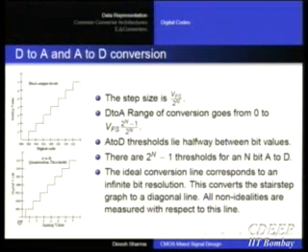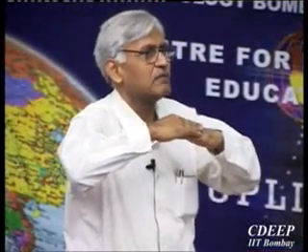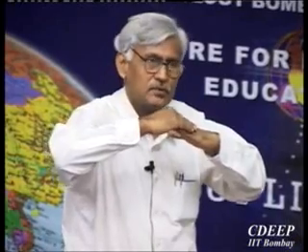Okay, this is the shift because the whole digital word spans an entire range. Okay, so this part is important. Sometimes when you have feedback, this could be even significant. Now, if I had a very large number of bits, then what will happen? This step size will become smaller and smaller. In the limiting case, if I had infinite bits, this would become just a diagonal straight line. Okay, in both cases. That means that the half bit offset will also now become 0. Correct?